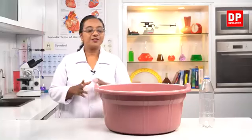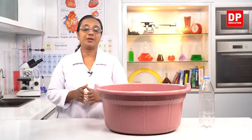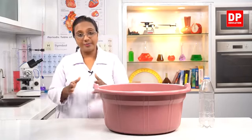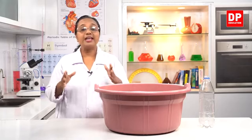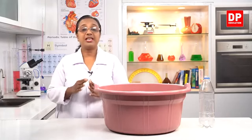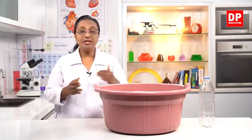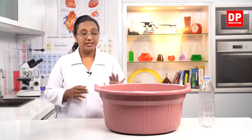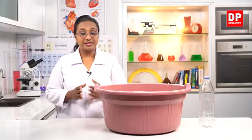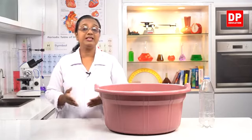Okay, students. So now we will try to demonstrate another characteristic of hydrostatic pressure, that is pressure exerted by liquids. I will demonstrate to you all that the pressure at the same level is the same value. So the pressure exerted by a liquid at the same level is the same in all directions. To do that, again we need to have colored water. Normal water is sufficient, but as I told you all before, when we have colored water, the visibility is better.